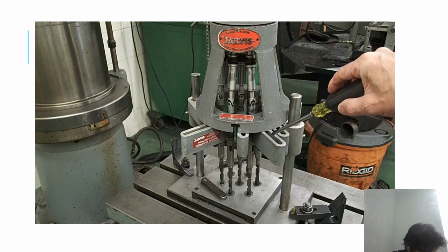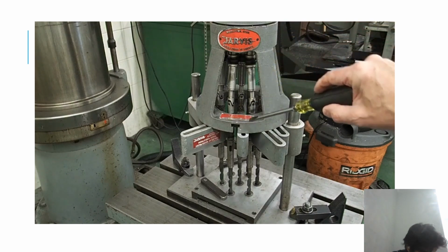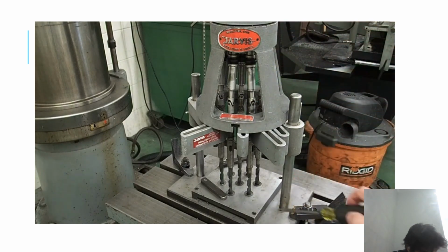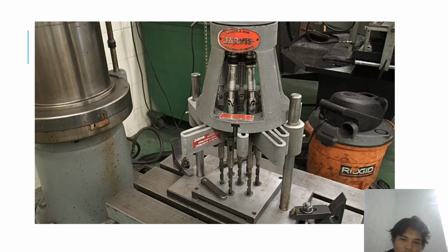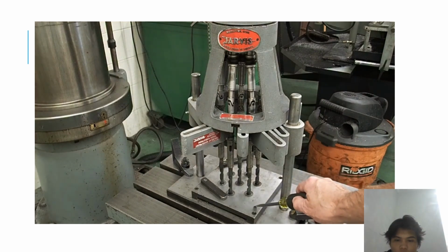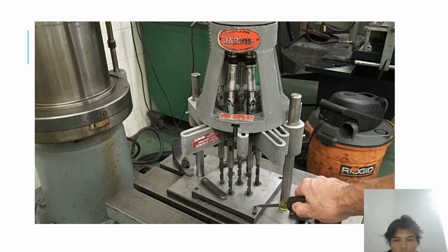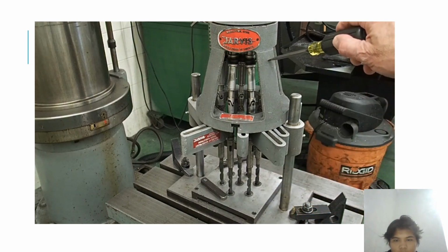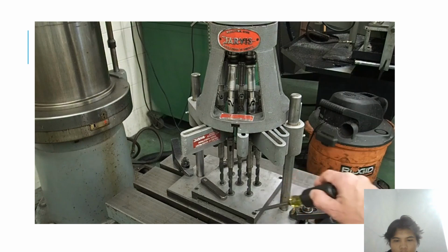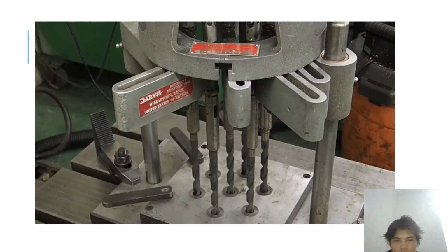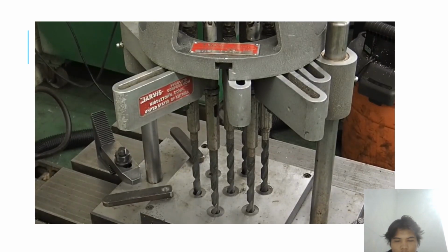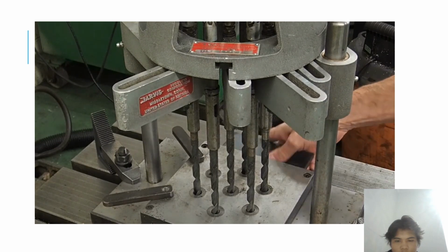The drills will each drive, and then down below we have a jig. In this case, the jig is set up to cut 6 holes at a diameter and 1 center hole. If you wanted a different configuration, you would have to make a different one of these jigs. So the multi-spindle drilling head is up here, and the jig is down below. We'll put a piece of plate in the jig, and we will drill a hole pattern on it. So it'll go in.